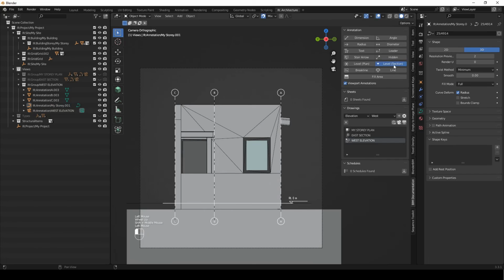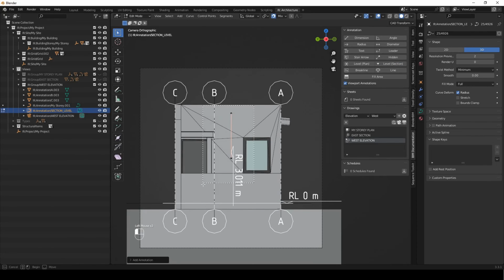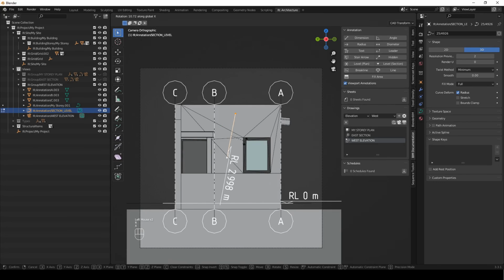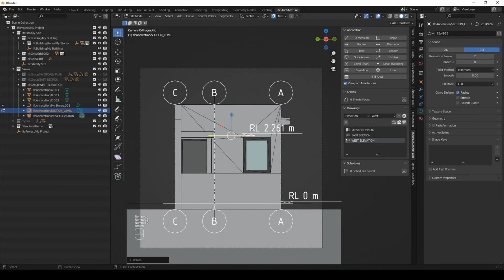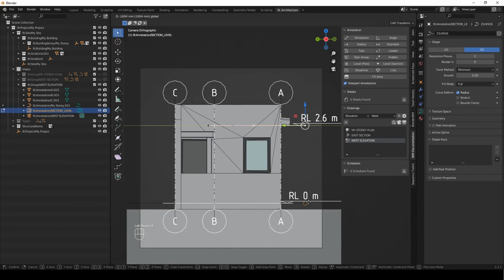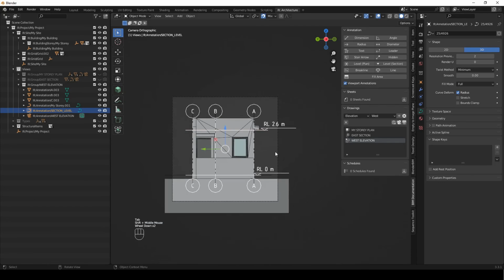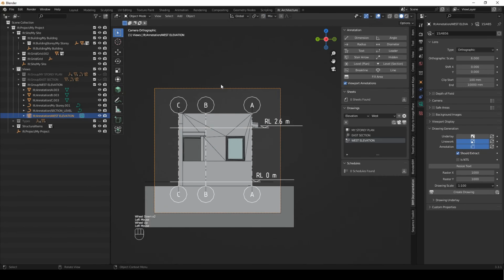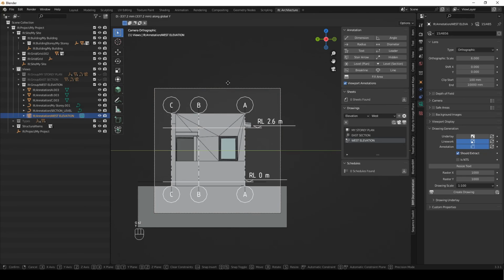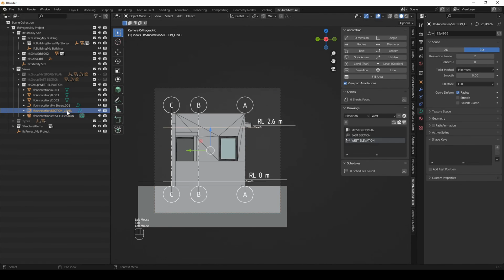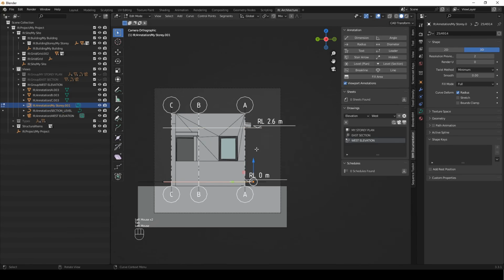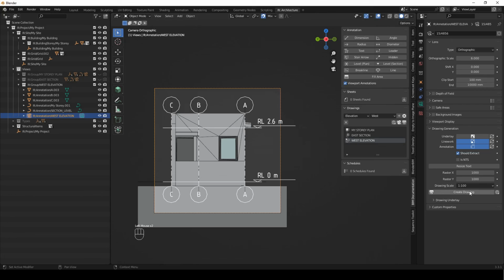I'm just going to add another level line. We're going to grab it, rotate X minus 90, bring it up to 2.6, snap it so that it lines up outside of this. I think this is going to overlap, so I'm just going to say GY, bring it to the side again, select my initial story level, snap these guys so they line up. Ooh, always turn your snaps back on. And then I'm just going to make sure, yeah, we said 1 to 100.